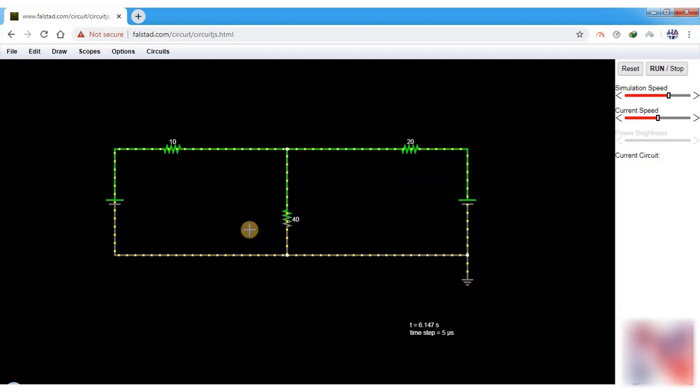So as I mentioned, there are 2 ways for verification of KCL. First method is that we go to individual components and check the current drops there, and after that we add those current drops at the respective node, either node B or node A. Or the second method is to place ammeters at the respective nodes and then we check the current drops. Let's proceed with method 1 first, where we go to individual components and check the current drop there.